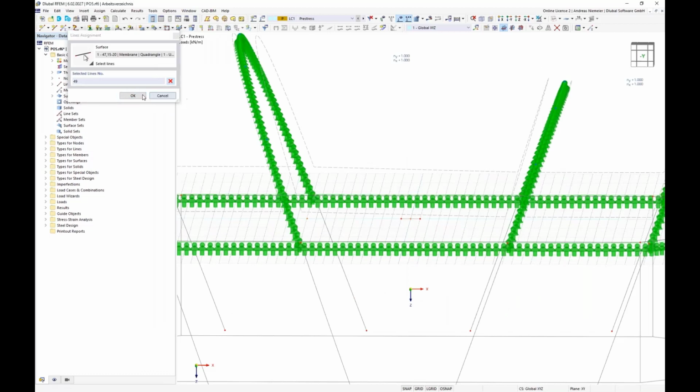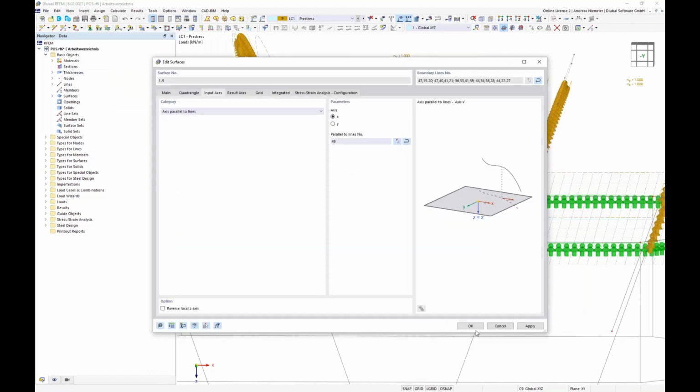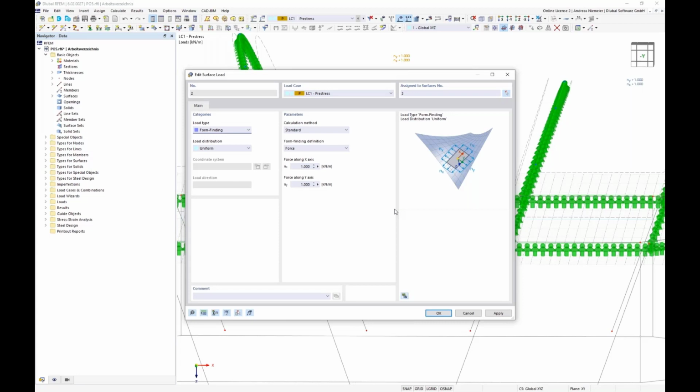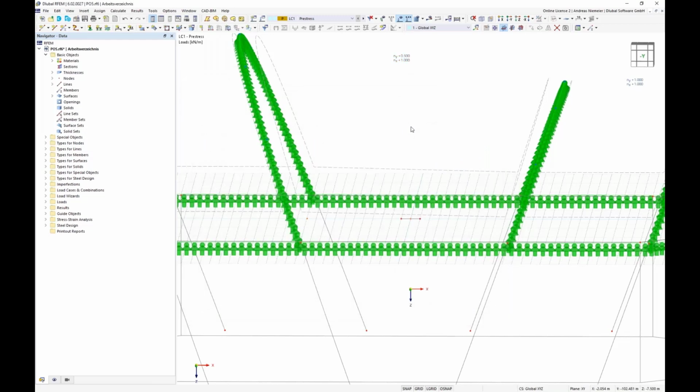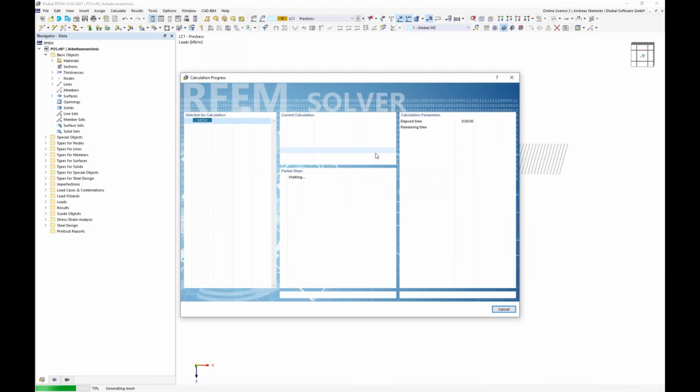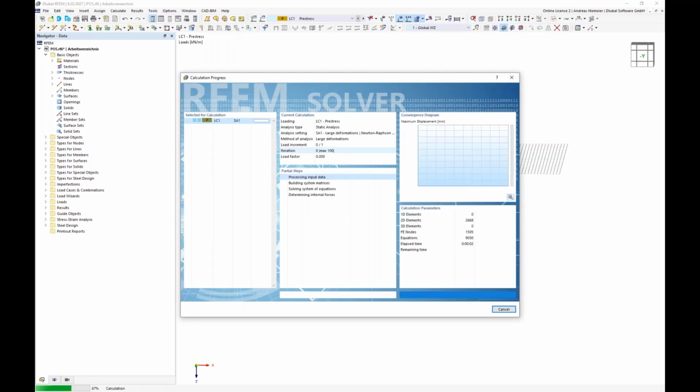And now I know, okay, x is running between arcs horizontally, and if I open the pre-stress here, I can reduce, for example, the tangential direction to 0.5. And if I run this again, we hope we get another shape. Let's see, it's converging, it's an iterative process, of course.